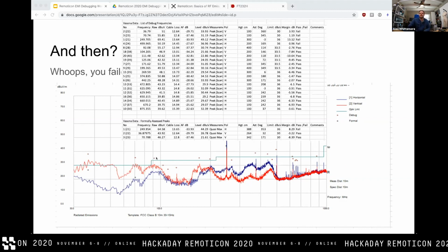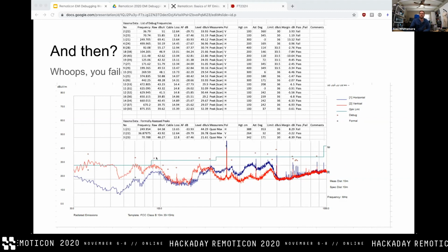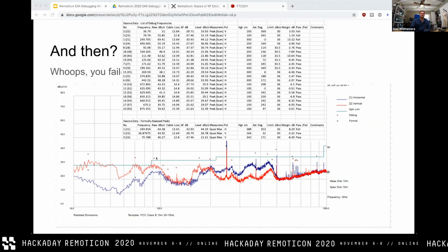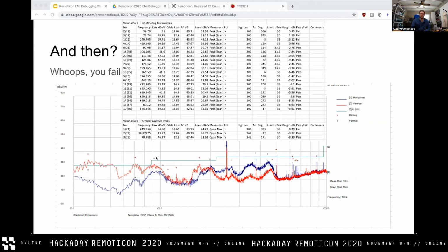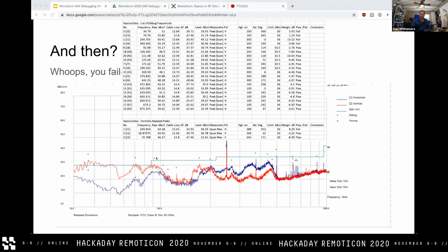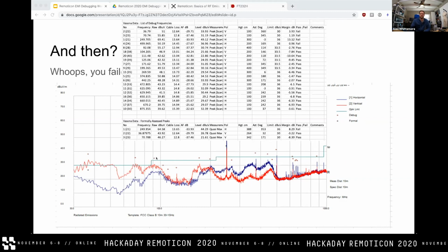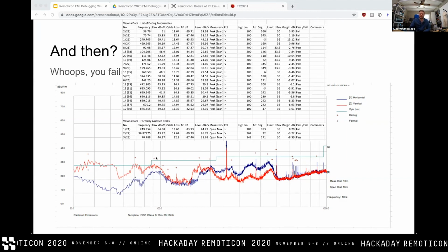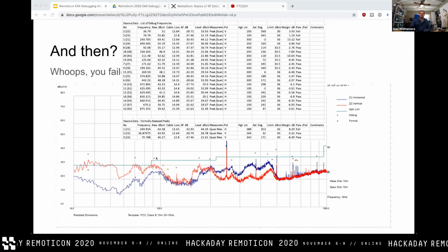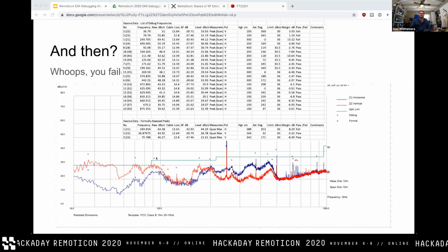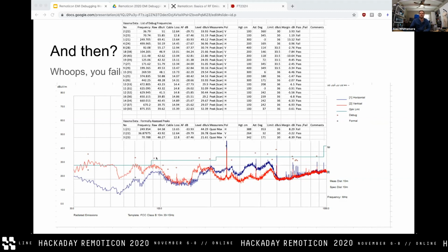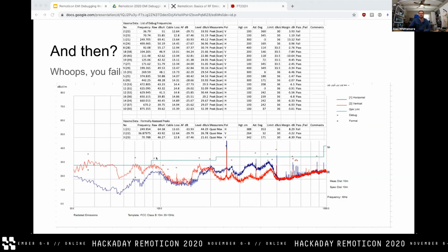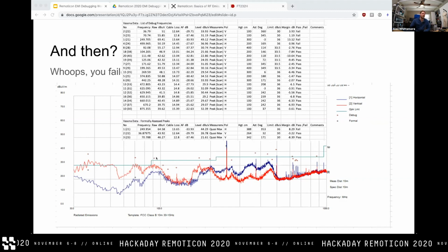Maybe your device is chirping really loudly for a moment, but it doesn't do that all that frequently. And like maybe your device only makes a loud burst of 250 megahertz when it first turns on or something like that. Or maybe it does it for 1 millisecond every 100 milliseconds. And it turns out that doesn't actually really cause any interference on any adjacent devices. So even though the peak is really high, the power that matters as far as causing interference isn't actually that high.